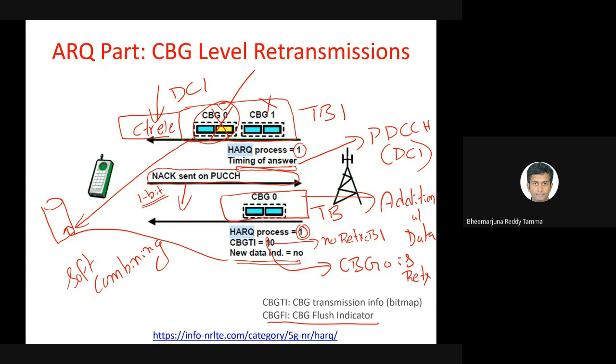That means we are not adding any CRC or any FEC bits when sending the NACK packet in uplink from the handset to the base station. So if this bit gets flipped from, let's say, 1 to 0, what would the base station think? The base station will think that everything is fine and it will send the next code block group. Yeah, exactly.